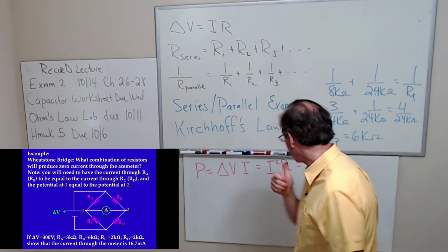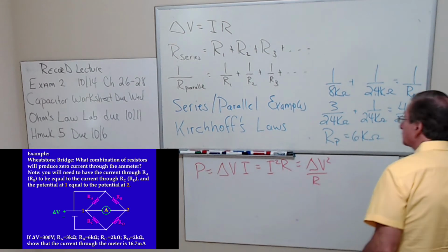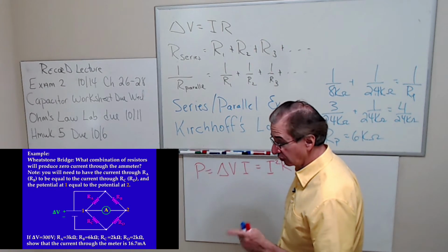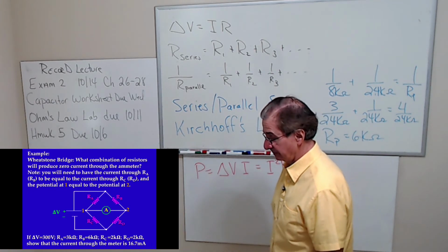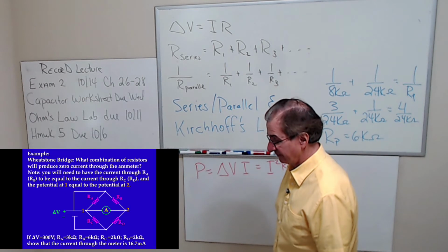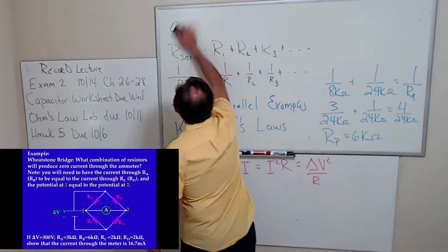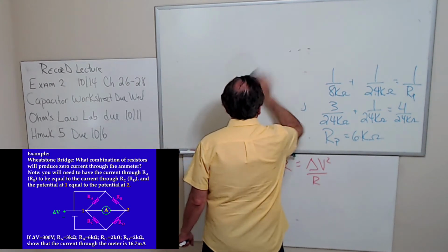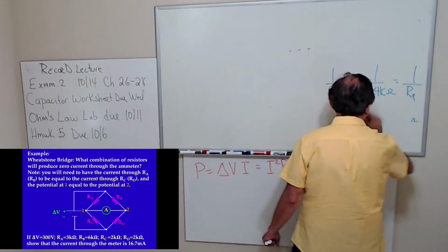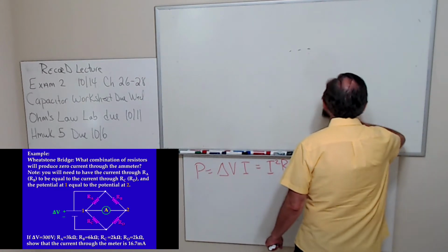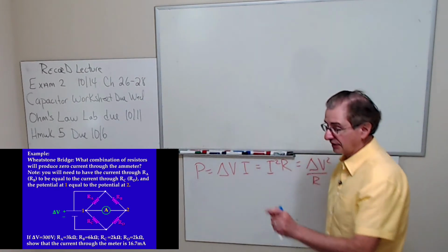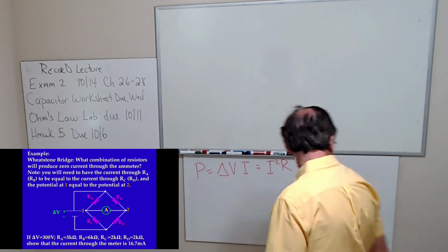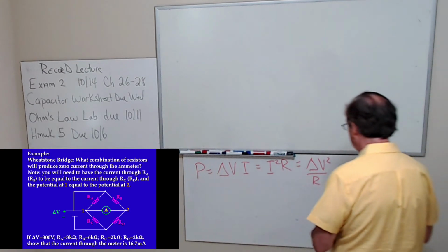Okay, good. A bunch of you chimed in on that one. So we're going to assume the ammeter has no resistance. That means points 1 and 2 are at the same potential. Well, actually, either way, they're going to be at the same potential, but assuming A doesn't have any resistance makes the analysis much simpler. Okay, so let me draw the circuit.